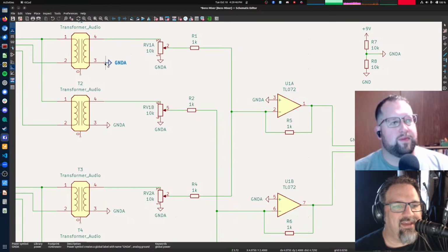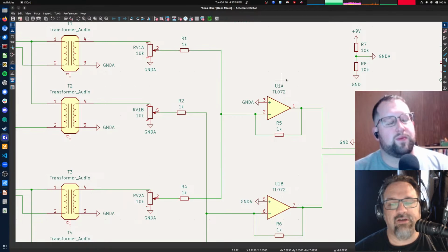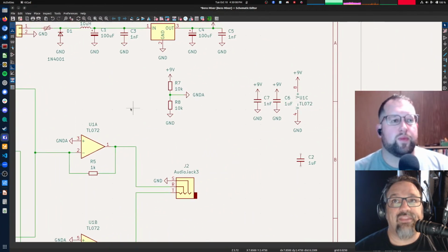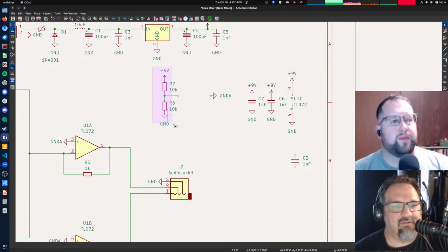It's also going to be a 10K resistor between here and here, right? So that is not what we want. We want to have something that is a very low impedance because the rest of the places that this voltage is used are relatively low impedances. So we need something that's going to make this VCC over 2 signal a much lower impedance.